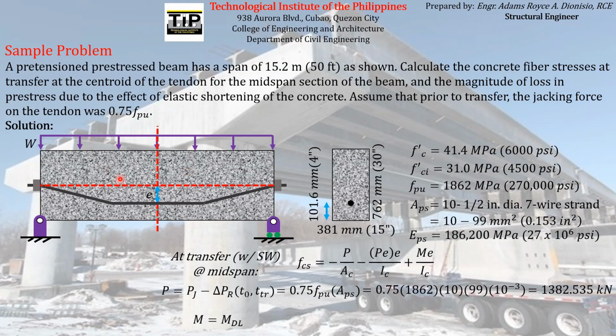But we know that if you want to find the weight of a concrete in terms of a uniformly distributed load, we can just multiply its unit weight by the cross-sectional area. We know that for a fact, even from our previous courses. If we want to find the weight of the concrete, which has a unit weight equal to 23.54 kilonewton per cubic meter, we just have to multiply that unit weight by the cross-sectional area to find the weight of the concrete per meter or per length.